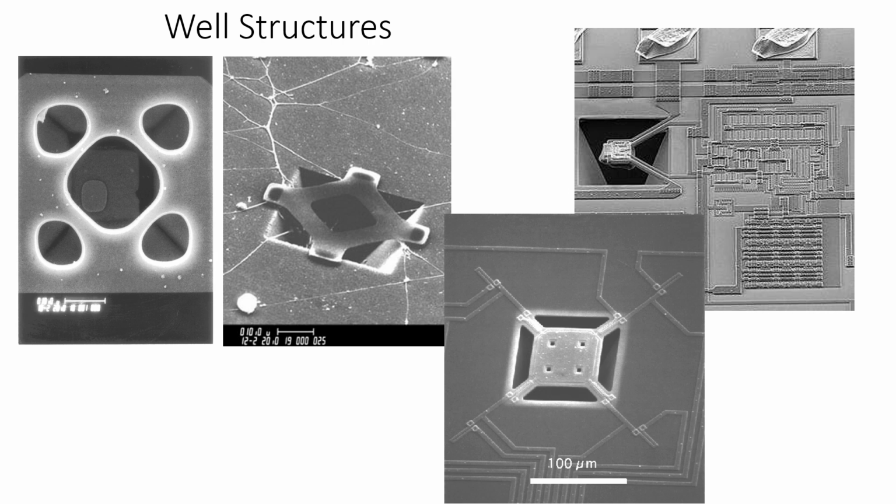Using this inverted cavity trick, you can create a lot of interesting structures, such as this cavity with a grid on top, or this one, or something like this. Here you can actually see that the cavity has an undercut because this edge appears to be white. It's white because the scanning electron microscope produces electrons that charge the mask, which is non-conductive.